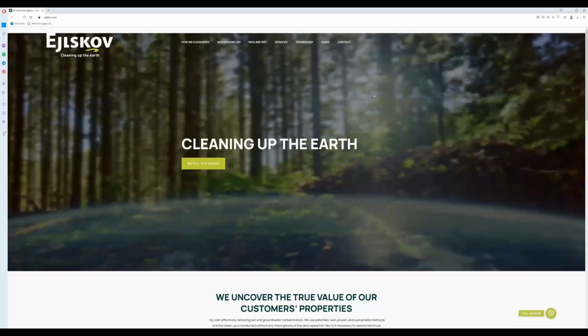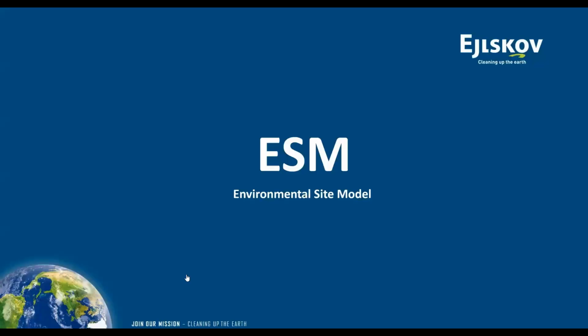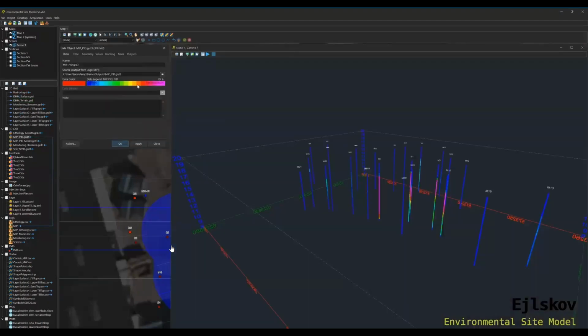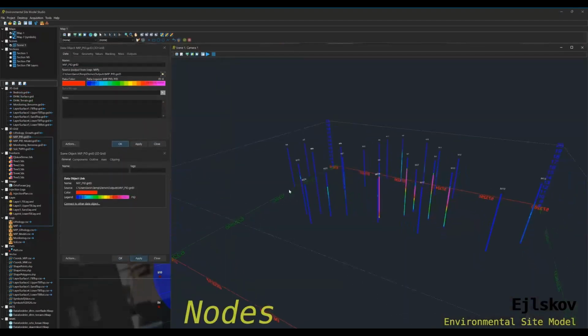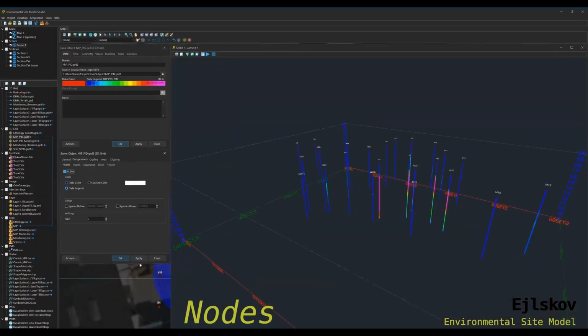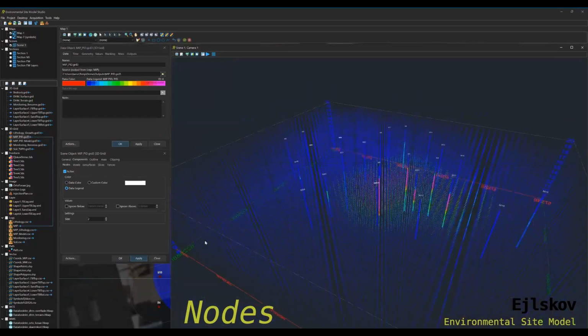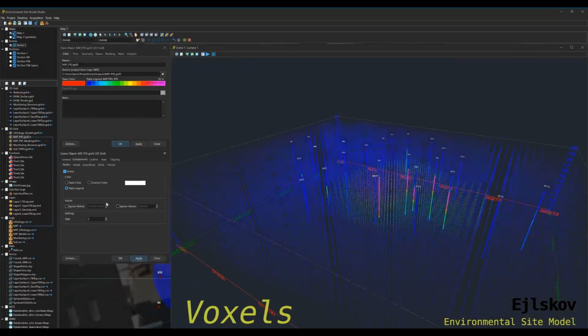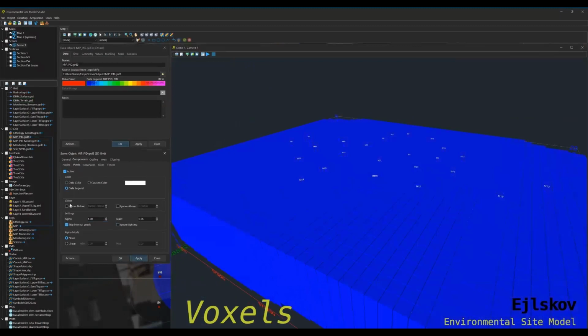You could use some of these same high-res techniques. For example, we've sampled below creek beds or stream beds, which would be somewhat similar, but we have not translated these techniques into a sediment sampling program. I could see that they could. Folks have used the MIP and those sorts of technologies off barges, and drilling gets done off barges, so theoretically you could translate that into a more sediment-focused sampling program.